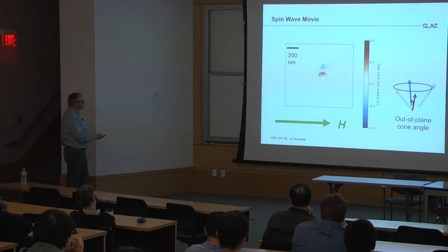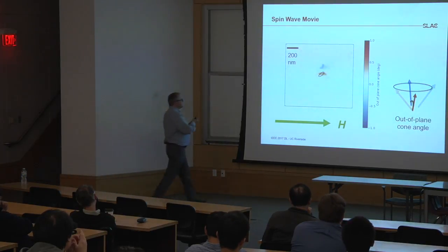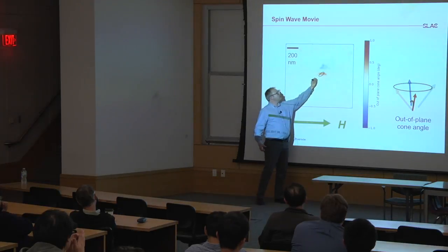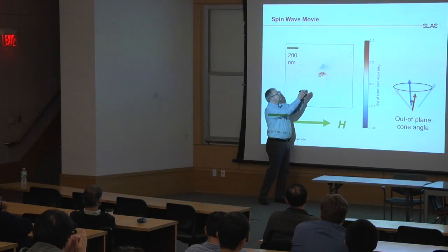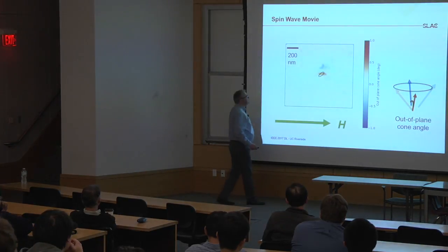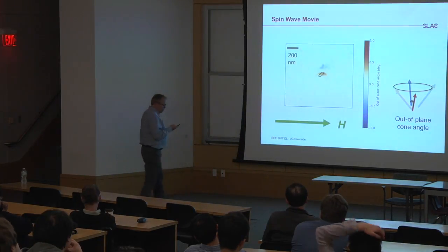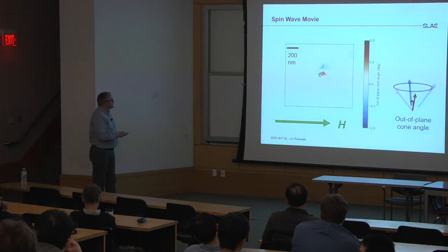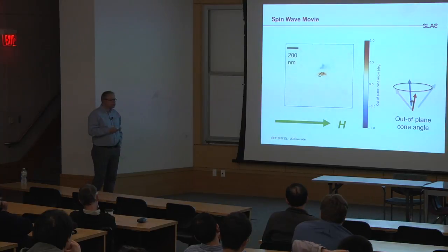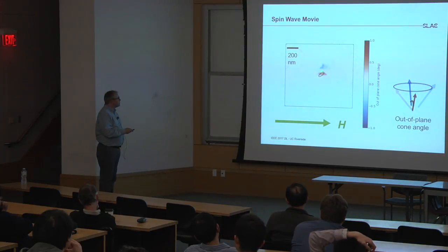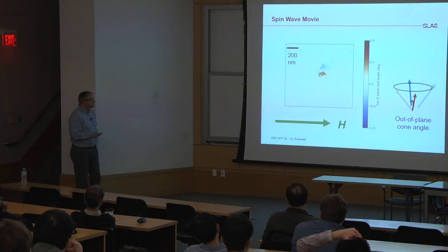There's a nano contact, and the current runs from the bottom layer through this nano contact, and then disperses into the extended ferromagnetic film. This is where the spin polarized current is injected. We were always thinking that everything should be localized to the area where the nano contact is.